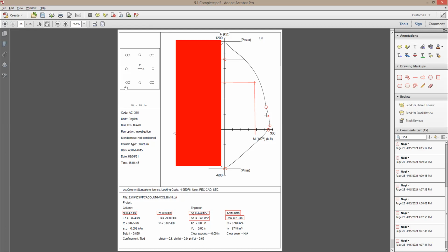Tributary area is going to be for each floor. This column here supports about, let's say, 900 square feet, 400 square feet, whatever number is going to be given to you. When you come right above the footing, you can add all of these forces and then find out dead load in terms of axial and live load also in terms of axial on the column.